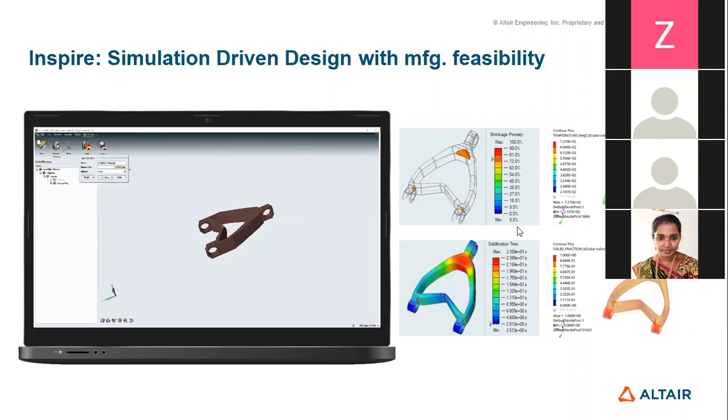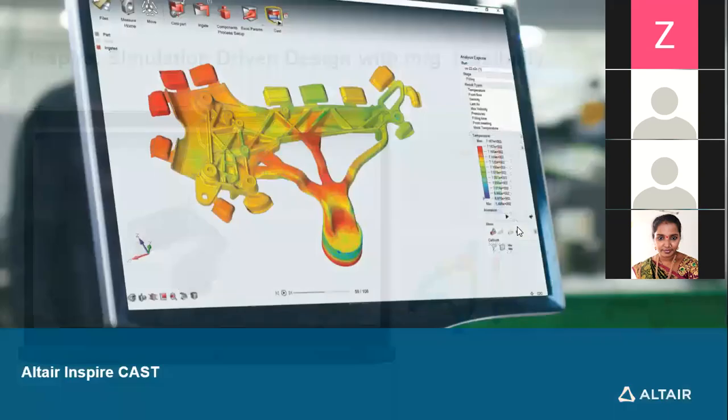Suppose you have a 2 mm thick part that is getting deformed under a particular loading condition. You want to optimize that part, but you do not want to increase the thickness of your component, because if you increase the thickness, it may affect your product efficiency. So if you optimize this type of sheet metal part, the software suggests the bead pattern. Once you apply the bead pattern to your component, it gets more stiffness than the plain one, or the previous one. So that was about the concept design, concept generation.